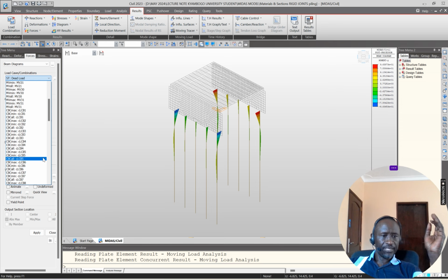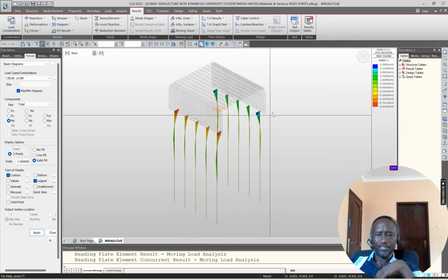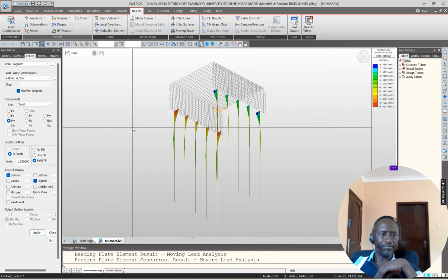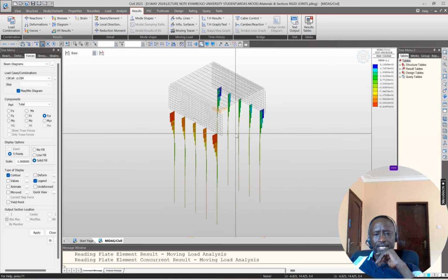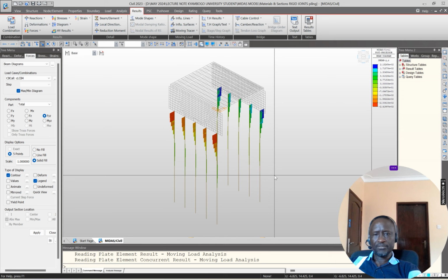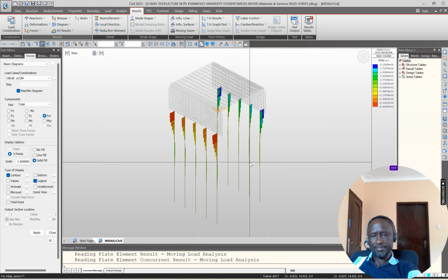But normally if I do my combination load, which I think after modeling you would have done, it is about 490 kilonewton meter at the joint between the vertical wall and where your pile starts. Then for shear forces, these are your shear forces. Now this pile you simulate using spring constants in the X, Y, and Z direction. Then at the bottom, I assume that it is end bearing, so it is combined. You have both friction and end bearing.